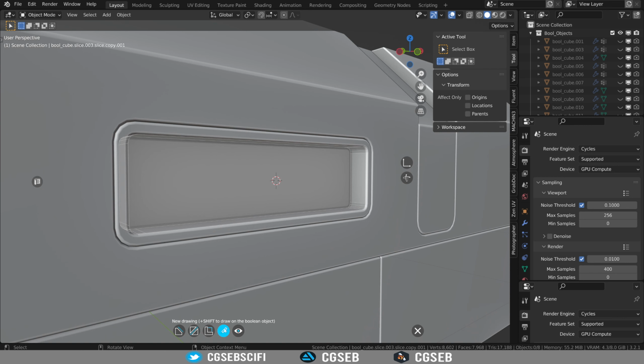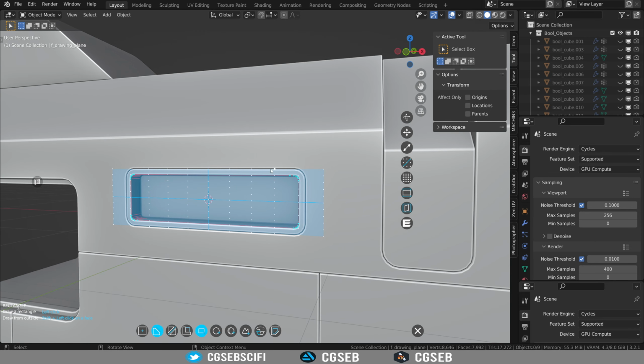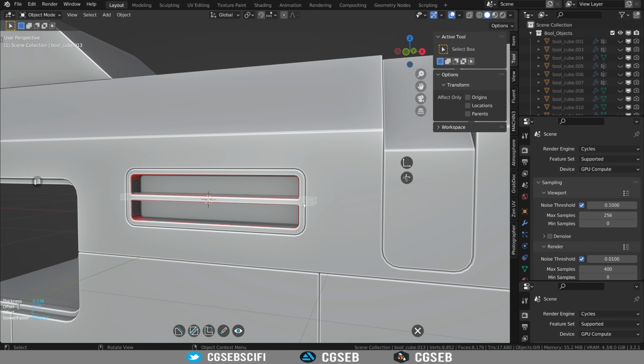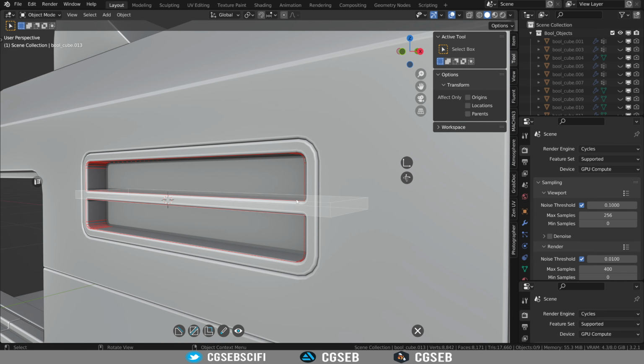And you can just shift click on the pencil icon, and this will allow you to draw directly on the cut that you're making. So that's a technique that we call cut the cutter in the Fluent community, and this will allow you to cut the cutter, which will actually reveal what you just cut. So that's a nice technique.